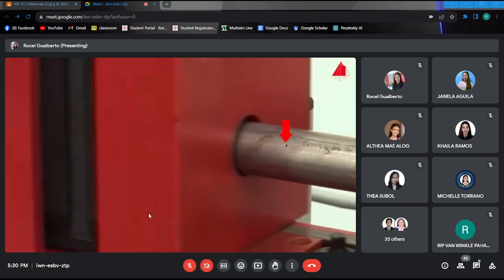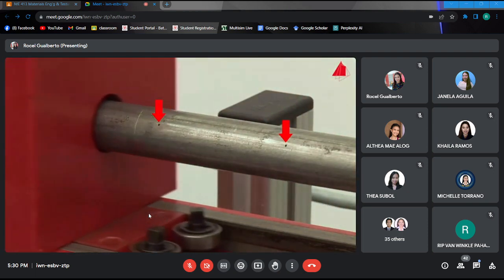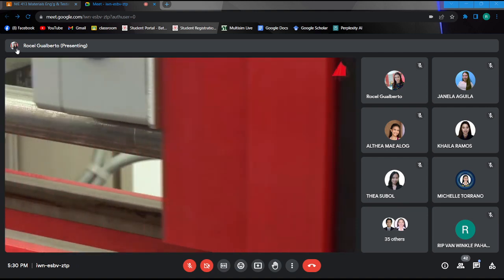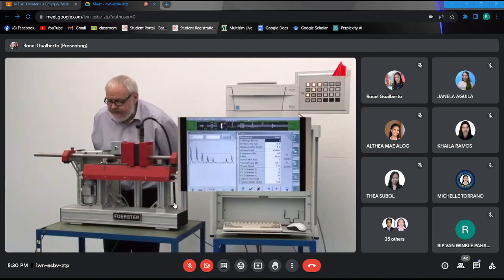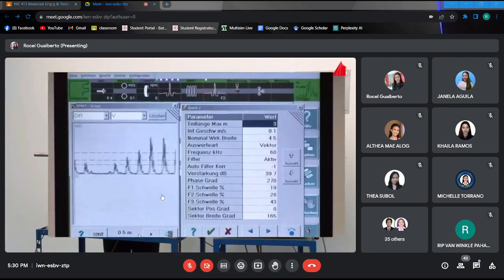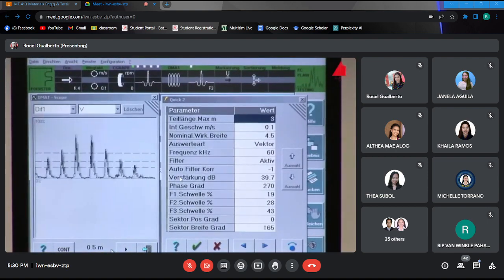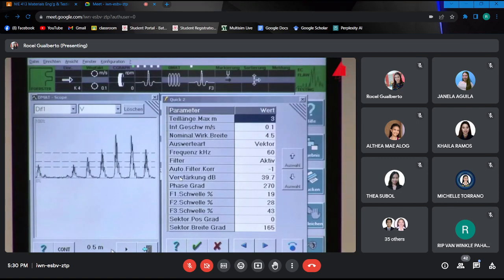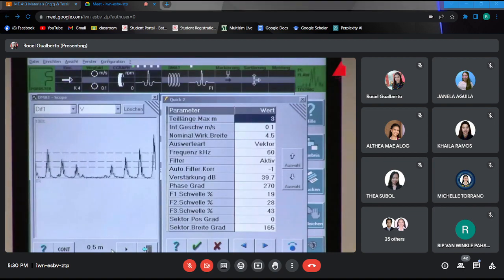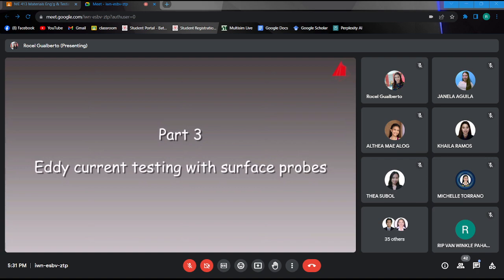By choosing appropriate test parameters and an optimized evaluation method, not only the locations of the holes along the axis may be determined. The diameter of the holes can also be measured approximately, a really neat feature. But one thing cannot be determined with this coaxial probe. It is the location of the defects in circumferential direction. Here we need another version, the eddy current testing with surface probes.